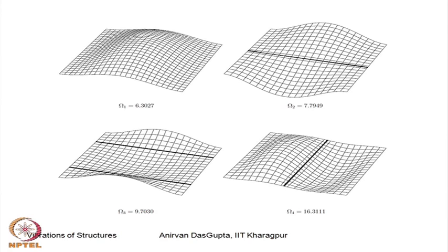In this figure I have plotted the first 4 modes of the plate. You can see that these straight edges are the clamped edges. You can see the displacement, and of course, the displacement and slope will be 0 there because the geometric boundary conditions have been satisfied. Here this is a stiffened edge.